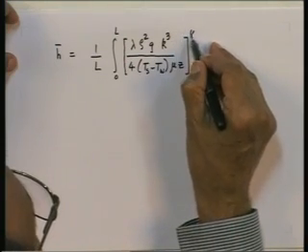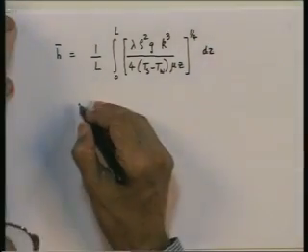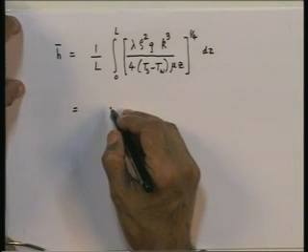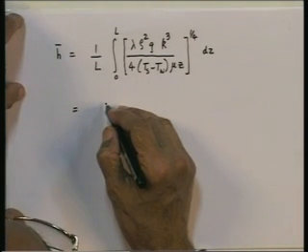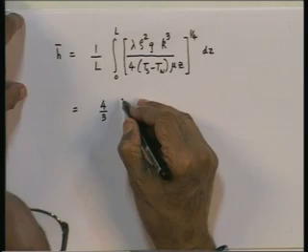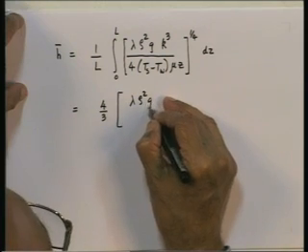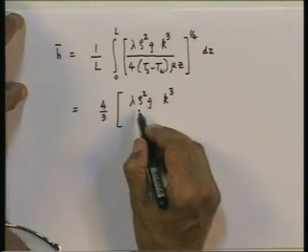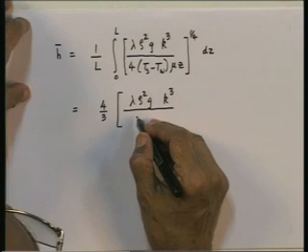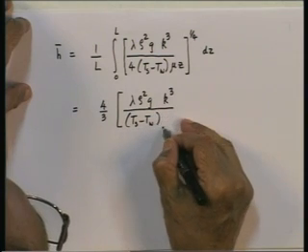This is my expression for h into dz. And on performing the integration, which is very simple, I will simply get this is equal to 4 upon 3 lambda rho squared g k cubed divided by T s minus T w mu L.